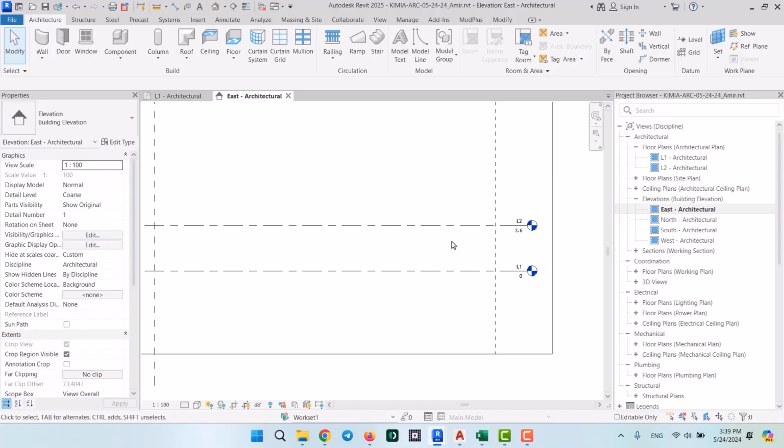But actually, here's a question for you. Do you know which level the main or basic walls start from? Like, from which spot or FFL should we start drawing the walls? Do they start from an FFL? As in, do they begin from the architectural floor? Definitely not. We need to draw the basic walls from the slab, which is at the TOS offset.